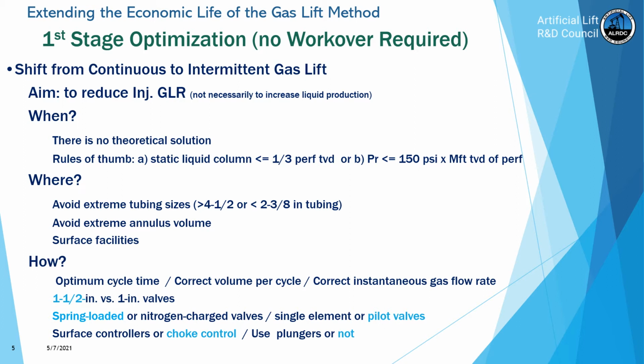Do we use a single element valve, or do we use a pilot valve? Well, of course, we prefer the pilot valve. In the upper section of the pilot valve, that's where we control the spread of the valve, in a way that is independent of the main port. The lower section of the pilot valve is where the main port is located, and it is always large, larger than any port that you will find in a single element valve of the same size.